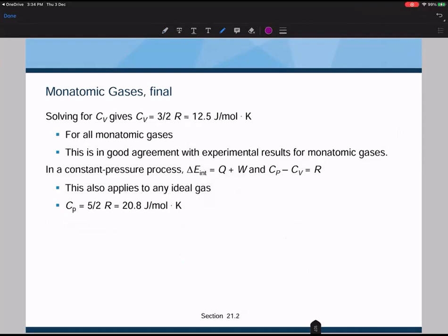And if you have a constant pressure process, on the other hand, then the corresponding molar specific heat has to be changed because work done is involved when you are undergoing a constant pressure process. Remember how you draw the PV diagram? You have a PV diagram. When you have a constant volume process, I to F, the volume does not change.